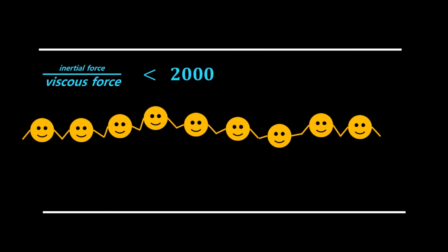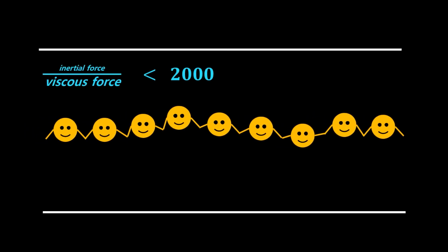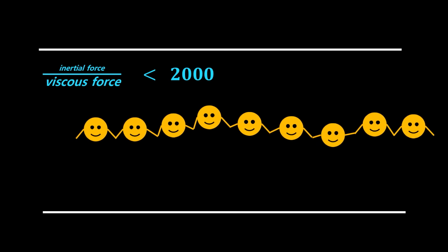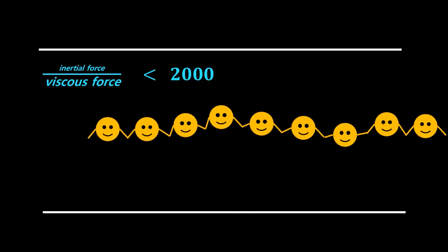But in reality, nothing is so orderly like that, and instead, this slightly shaky path would be a more accurate depiction of the flow. And those random little bumps are called perturbations, which can happen to anything with real mass and real velocity, and hence related to the inertial force of the fluid flow. When there is enough viscous force, which I imagine as fluid particles holding hands with each other, it basically dampens whatever small perturbations there are, hence looking like a laminar flow.